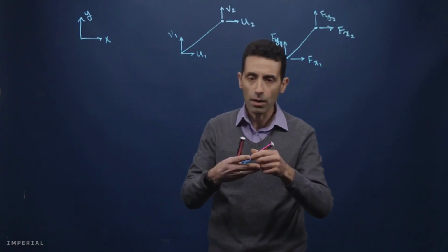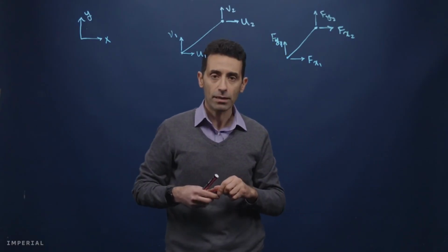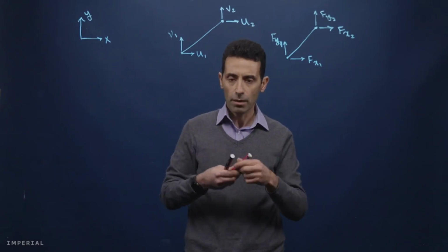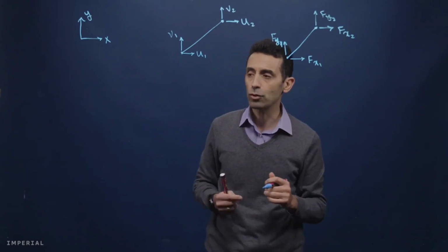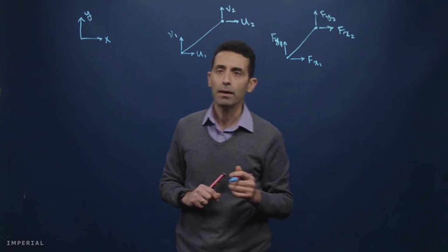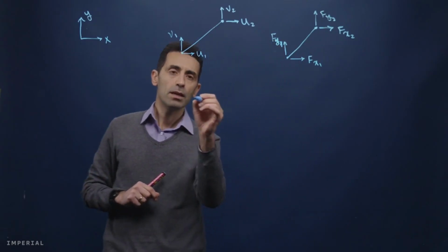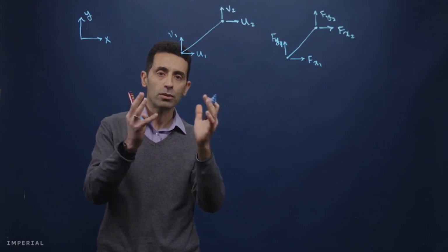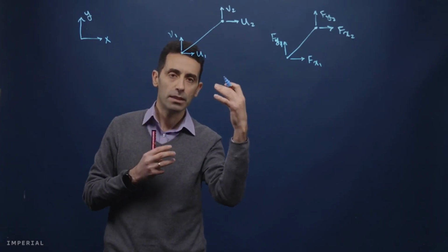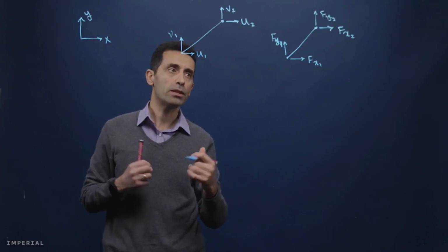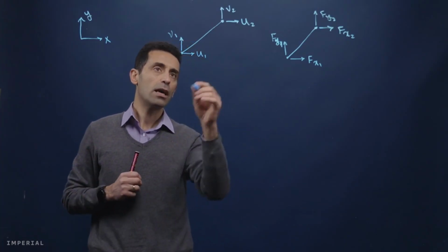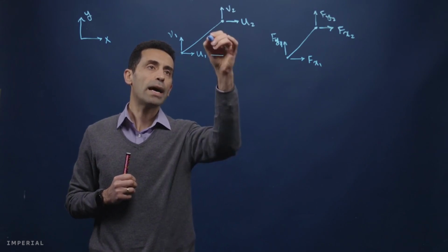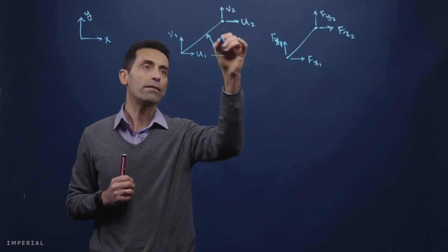Okay, now we need to again find the element stiffness matrix. I'm not going to derive everything for you, but I have it written. So essentially, we need to put together the geometry and the material properties into the stiffness matrix, but this time we have an element that is tilted at, let's say, angle alpha.